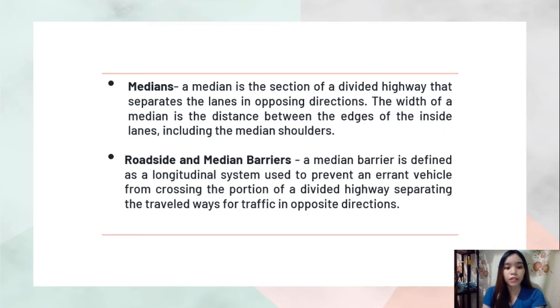So the functions of a median include providing a recovery area for out of control vehicles, separating opposing traffic, providing stopping areas during emergencies, providing storage areas for left turning or U-turning vehicles, providing refuge for pedestrians, reducing the effect of headlight glare, providing temporary lanes and crossover during maintenance operations.